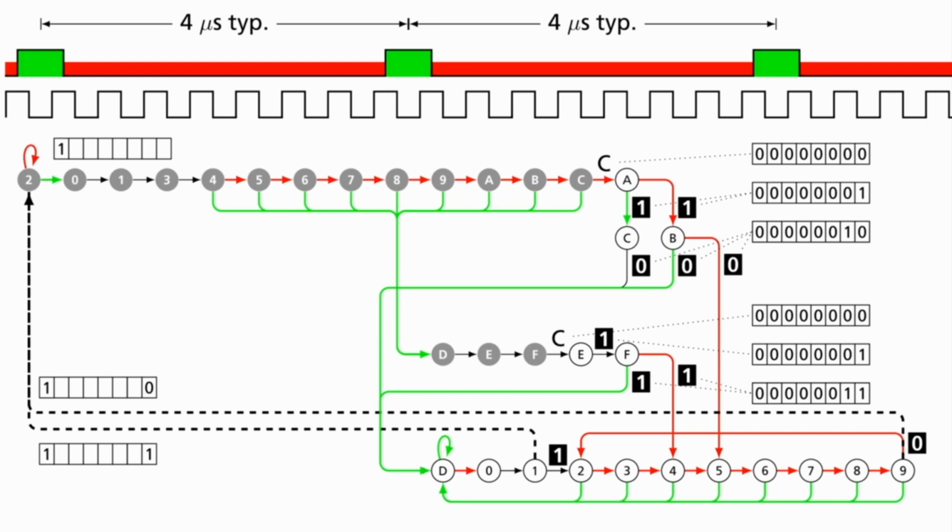There's one even bigger trick in reading a disk, synchronization. That is, figuring out where a byte sequence starts. As I've just shown you, if you start off waiting for the first pulse of a byte, this sequencer stays synchronized. But what if the processor starts reading in the middle of random bits? It turns out this sequencer will fairly quickly synchronize itself if you feed it a repeating sequence of 8 ones followed by 2 zeros. Credit where it's due, my animation of the sequencer comes from a drawing in Sather's book, which I adapted for this presentation.